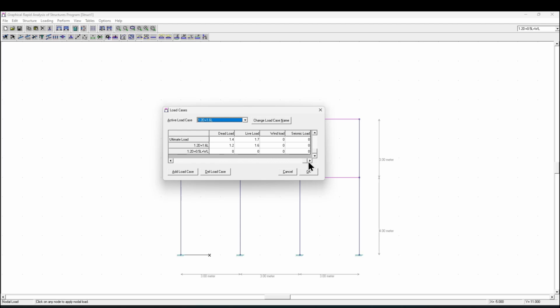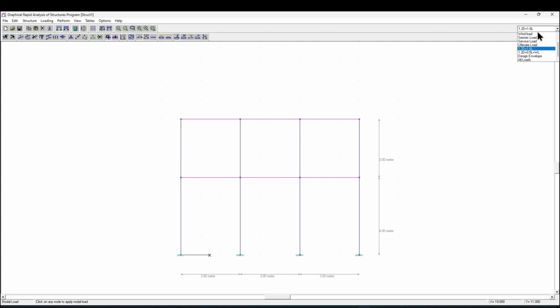And then yep, that would be all. And for this loading combination, 1.2 dead load, so type here 1.2, as well as for the dead load 1.2. Live load is 0.5 and wind load is 1. All right, so if you click on OK, that means it is now loaded. The necessary factors are already all accounted for.